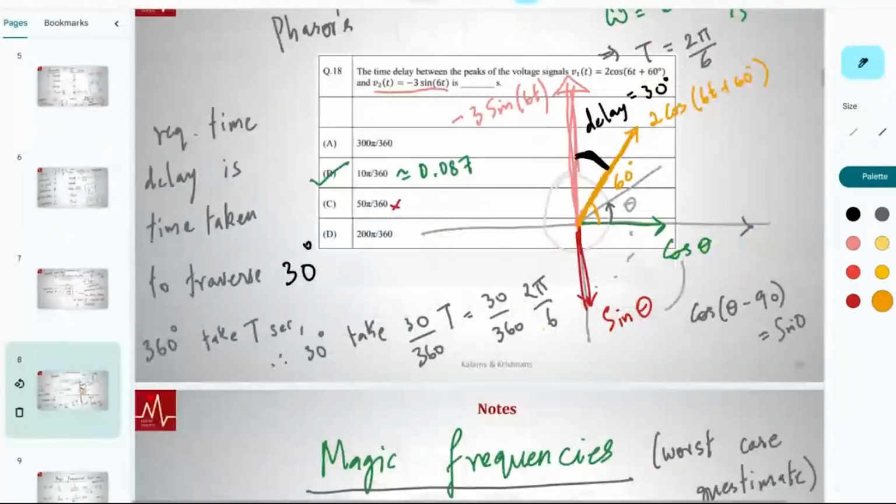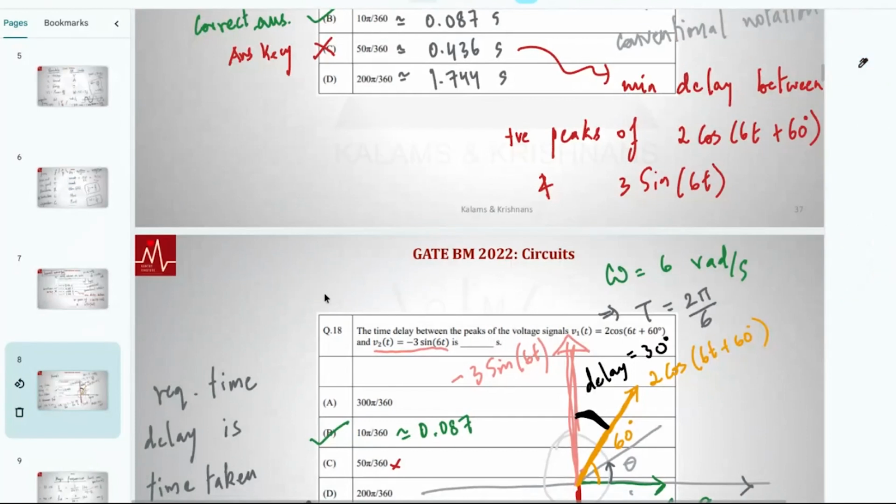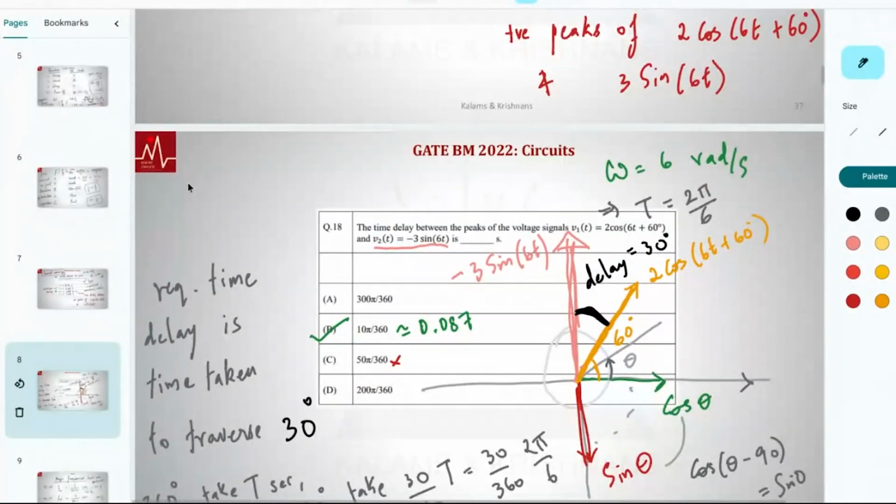You are good. Yeah, because sine and minus sine have 180 degree phase difference. Sine is negative y-axis, minus sine is positive y. Good question. The convention is x-axis is, let me also explicitly write that. Phasor convention. Your cos theta is x-axis. Your sin theta, this is minus y.